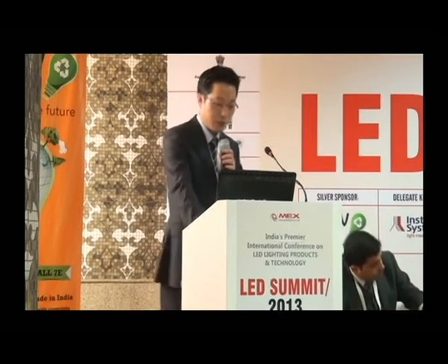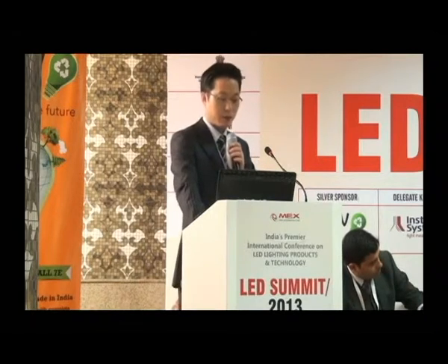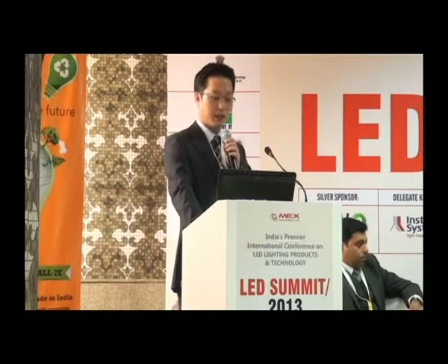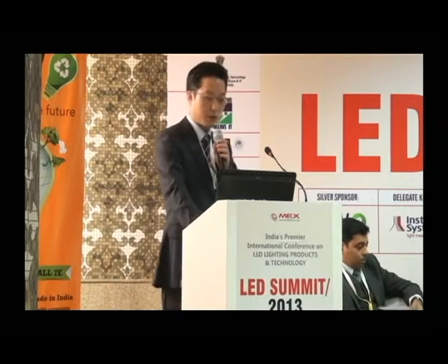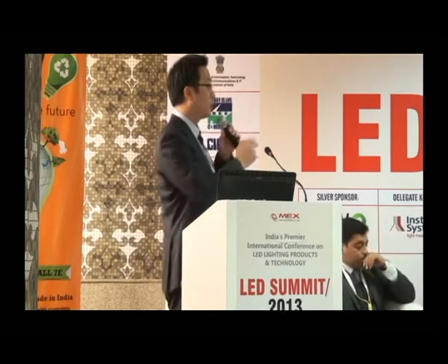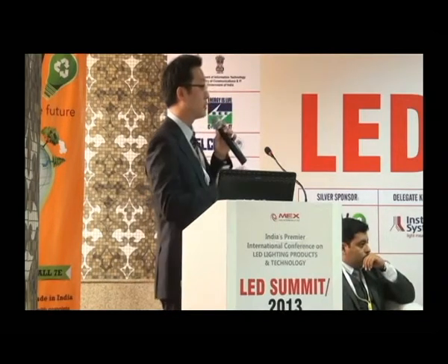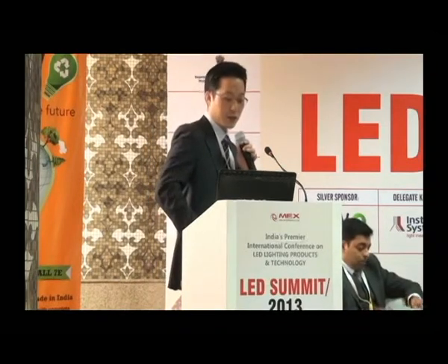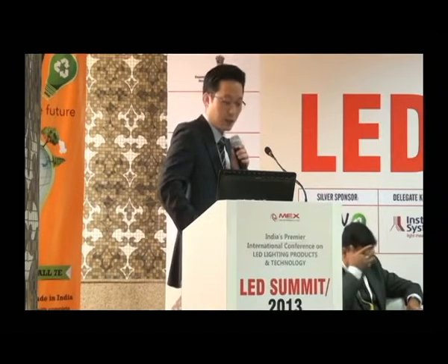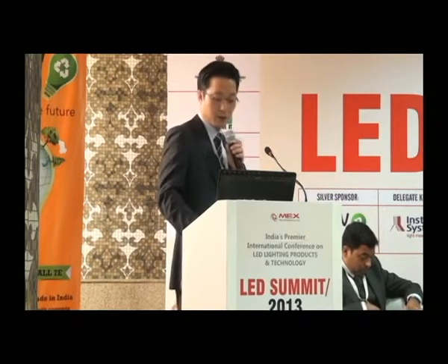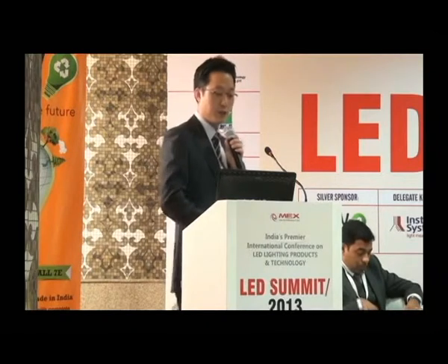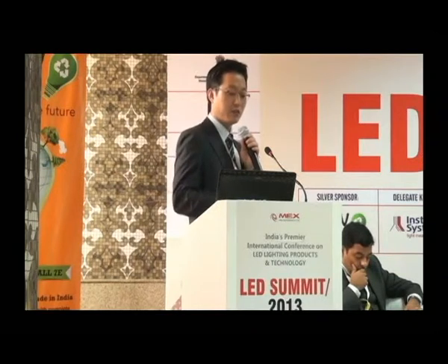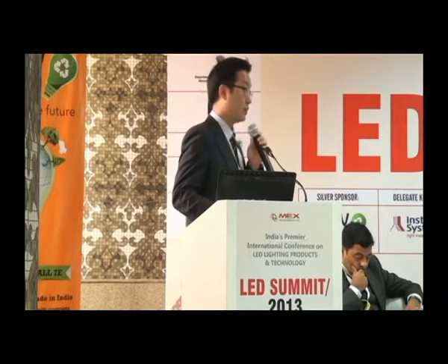Okay, so I would like to explain the silicone development trend for LED lighting. First, we separated the properties for silicone performance: one is refractive index, the others are sulfur gas blocking, heat stability, and price. In the case of phenyl-based silicone material, our main target is increasing thermal stability and then price.